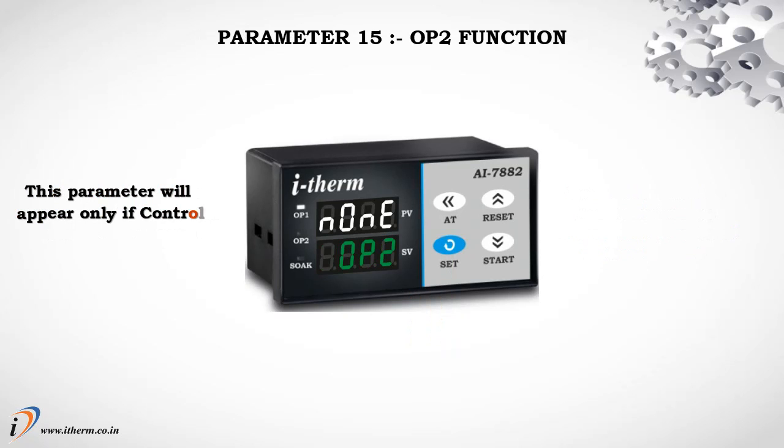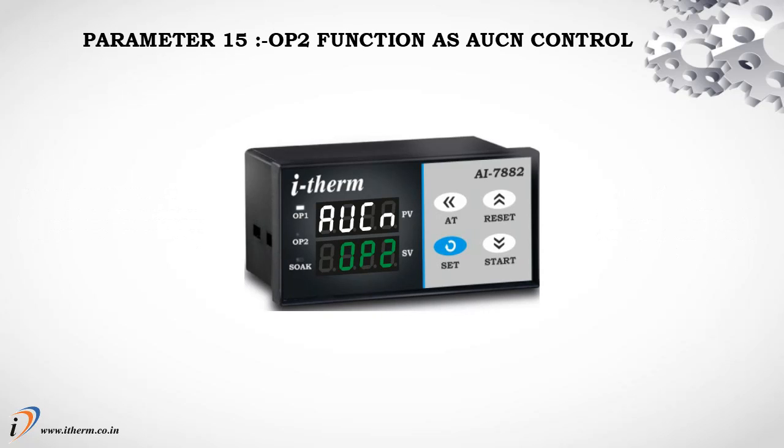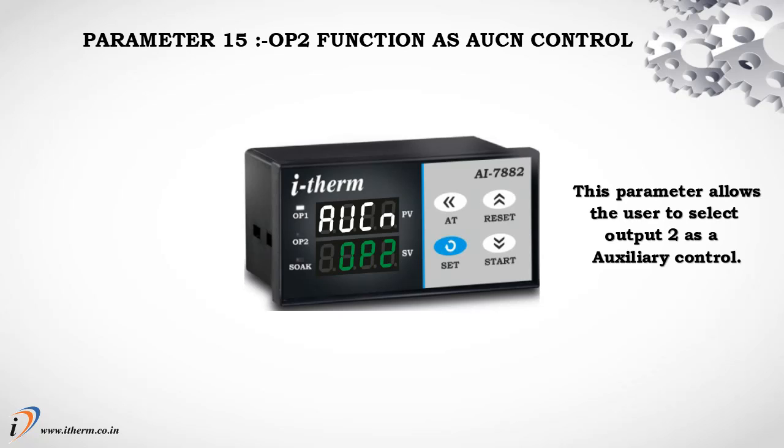Parameter 15, Output 2 function. This parameter will appear only if the control logic is heat or cool. When none is selected, output 2 will be permanently deactivated. Parameter 15, Output 2 function as auxiliary control. This parameter allows the user to select output 2 as an auxiliary control.